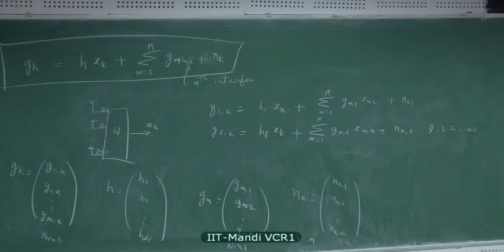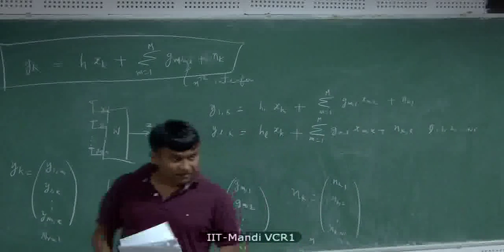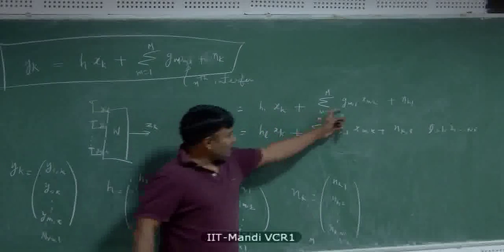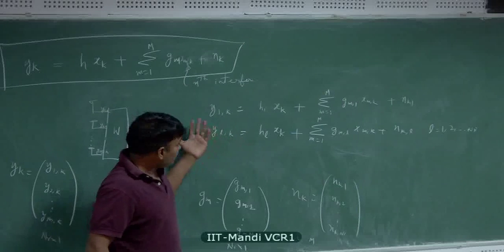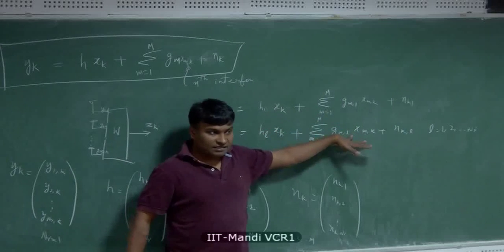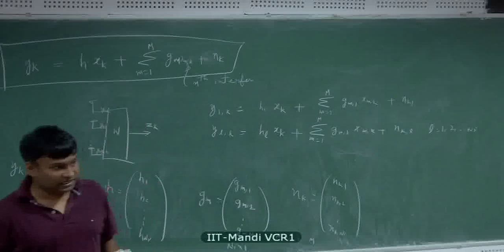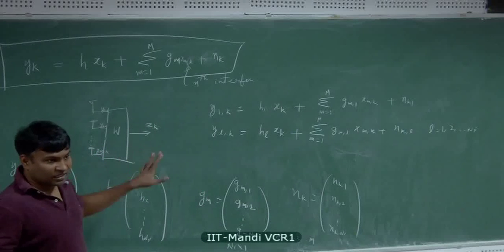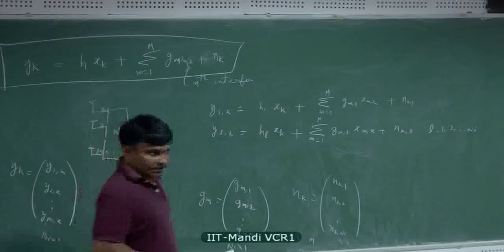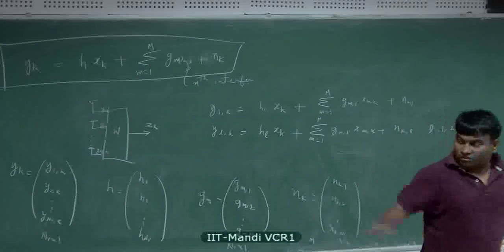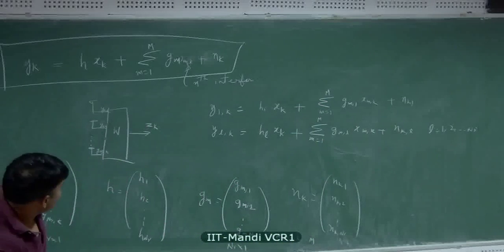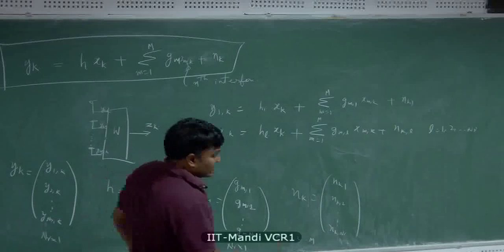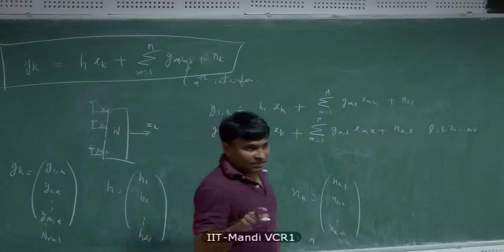Do you understand this model? It's very important to understand this model. If you don't understand this, it's hard to proceed. Basically, we're talking about receiving a signal and M interferers superimposed, plus thermal noise, at different antennas. What changes? The channel gains change, and they're all independent random variables in this particular case. And we're not going to consider path loss, shadowing and all those things. We don't have to include them right now. If you want, you can include them in these channel gains. So X M comma K, what is the meaning? K denotes the discrete time index.